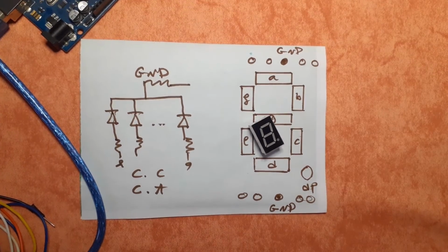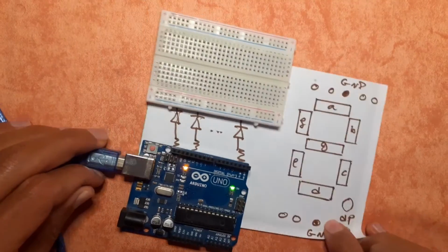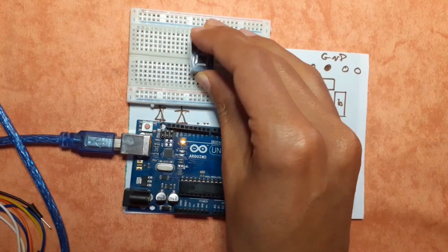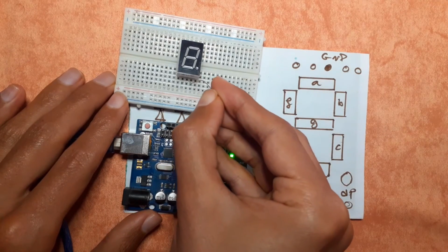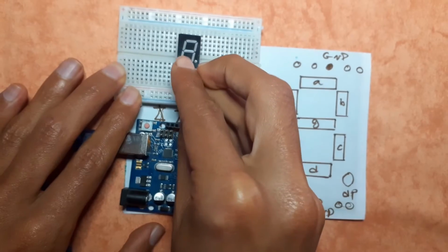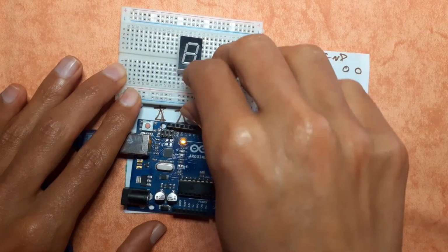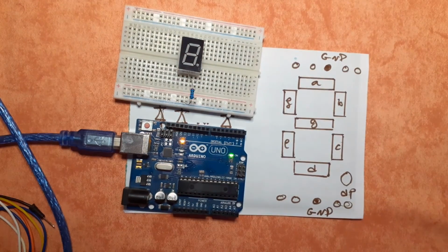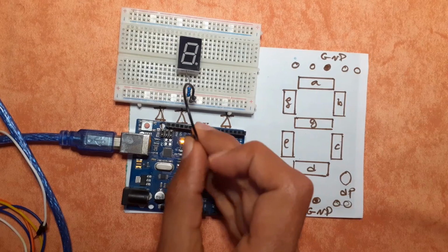So let's take the Arduino Uno and start connecting the GND. Of course, you will need a breadboard. After that, I will connect the middle leg to the resistor, and the other side goes to this point. Basically, we have all of these points that are connected to each other. We can hook up the other side of the resistor to the GND pin of the Arduino.